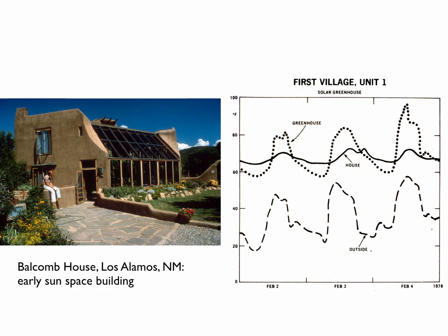But you also see the temperature profile for the house, which is really staying within a comfort range. It's dropping down to say about mid 60s and going up into the 70s. And these are winter days, right? So the house is actually floating, but it has a lower amplitude, right? And the idea is to keep the house within a range of the comfort zone that you could tolerate and be comfortable at. Maybe you have to change your clothing just a little bit, but you can see those three curves really illustrate what we're trying to do with any passive solar building.